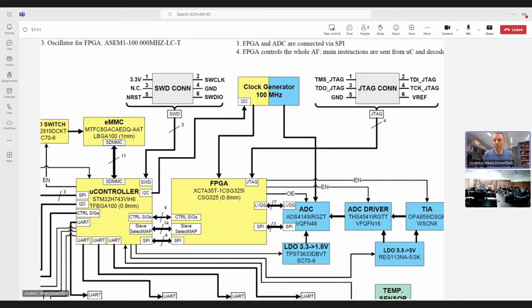You need to actually buy a shield, and it has one additional step in production, in assembly. You need to put it there. But in this way, we are just using the resources of the PCB, which basically have zero cost. If you add 20 more vias, it will not make a difference in the price of the PCB. So that's what we would like to do.